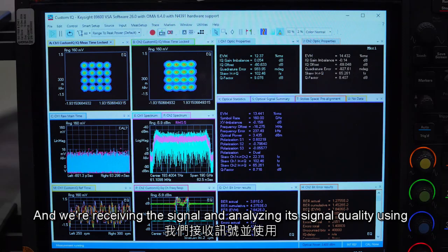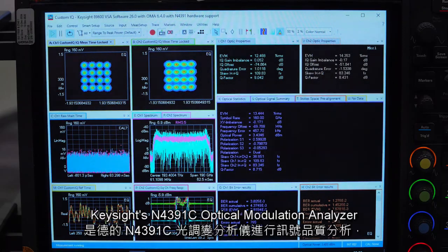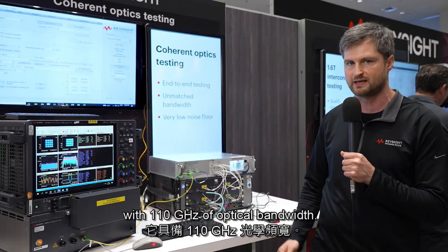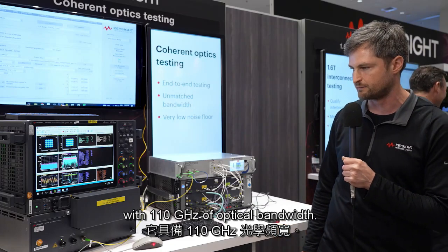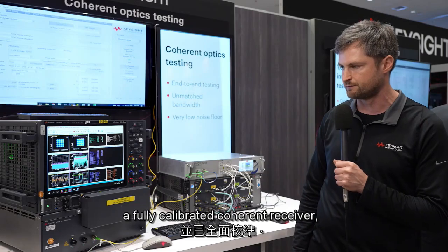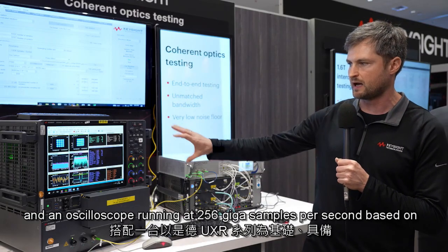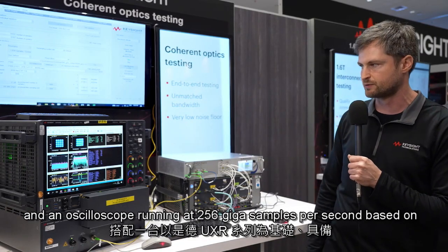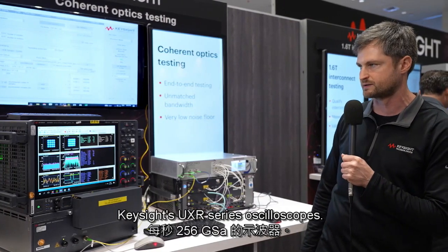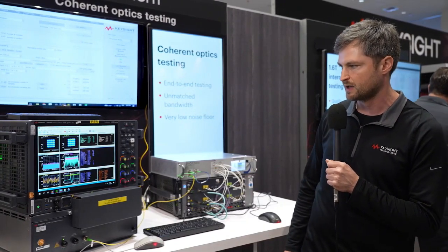And we're receiving the signal and analyzing its signal quality using Keysight's N4391C optical modulation analyzer with 110 gigahertz of optical bandwidth. This device comprises a full coherent receiver, a fully calibrated coherent receiver, and an oscilloscope running at 256 gigasamples per second based on Keysight's UXR series oscilloscopes.